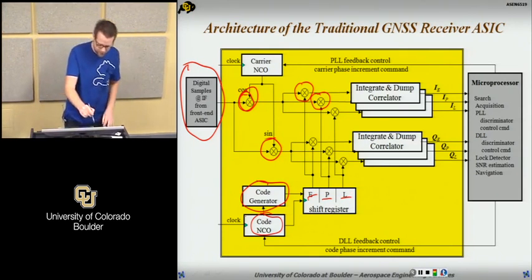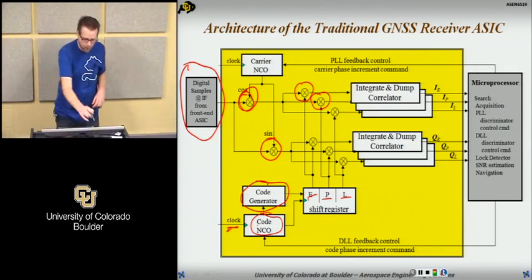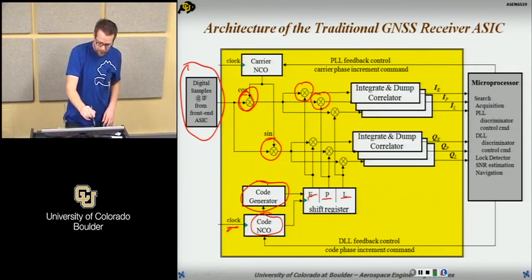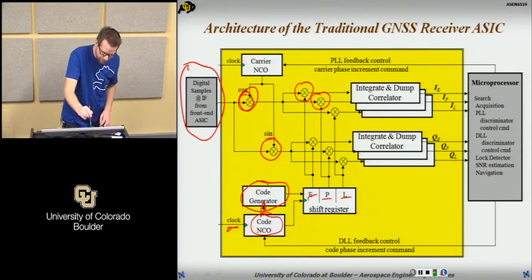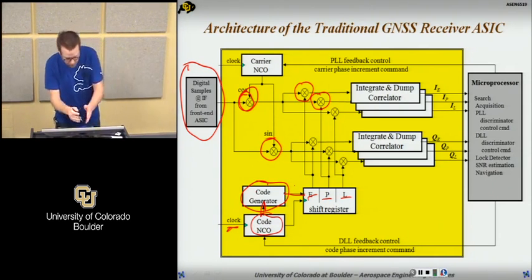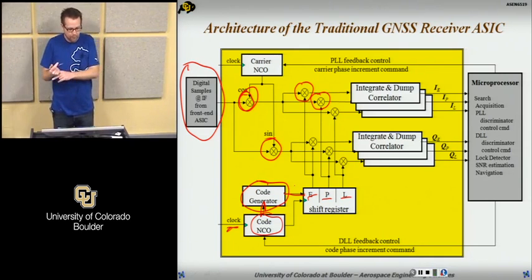We have a clock coming in, and then we generate another frequency based on that clock, and we can control how fast the code is generated. Does it make sense? Because that's what we want to control later on in tracking. But anyway, we get the code from here, and we shift it a little bit to get the early, prompt, and late three replicas.